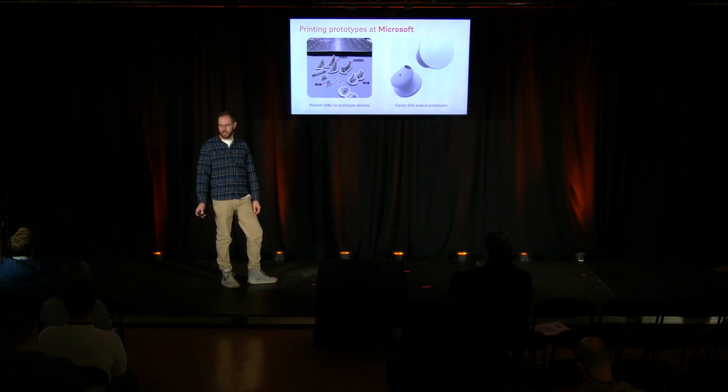And if you know polyjet, it's very brittle, or more brittle than we'd like to have for our models. And so where we used Formlabs for that, we used a lot of Tough 1500, Tough 2000 for the actual headband.